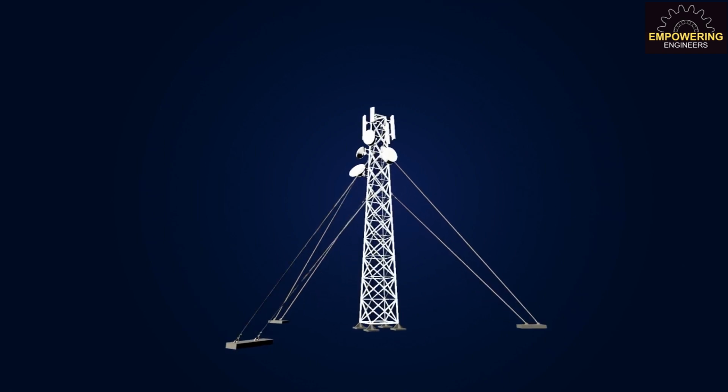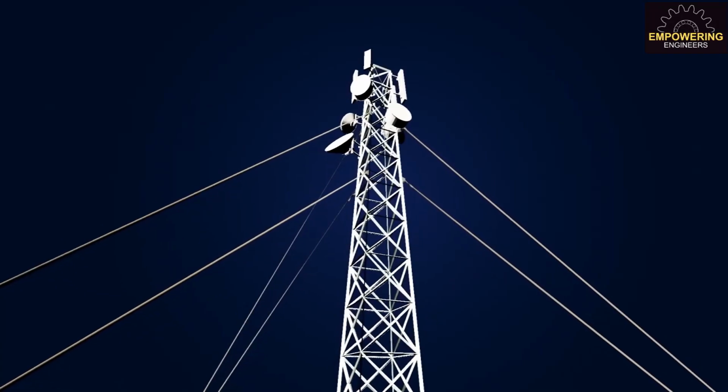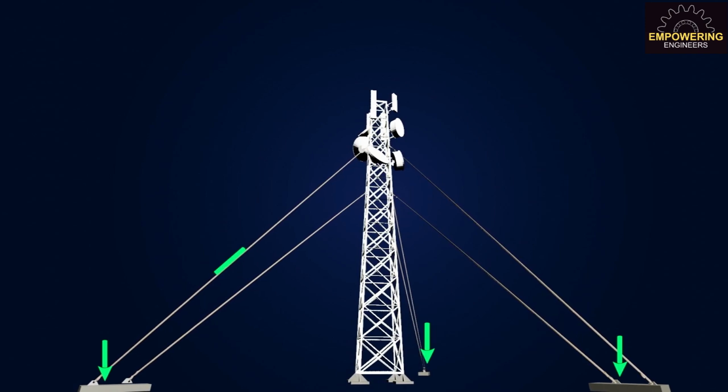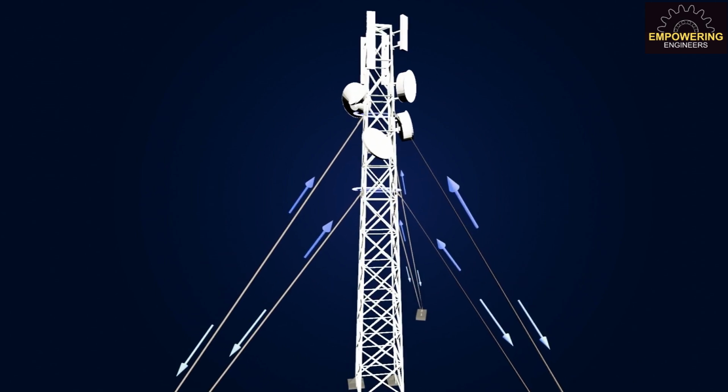Let's now examine forces that are not in a single plane. Wire ropes are used to stabilize portable mobile towers. Its position will be disturbed by wind load. These ropes are anchored in the ground, and their tension is adjusted based on the tower's deflection and wind force. These ropes pass through several planes before coming together at a single location on the tower. Non-coplanar concurrent forces is the name given to this force system. This system can be used to calculate the tension force in each rope.